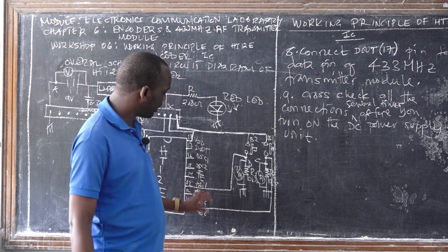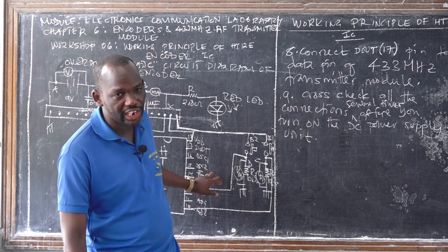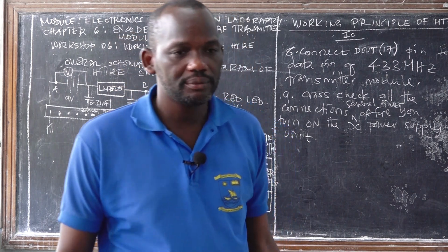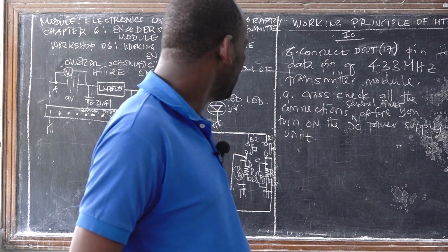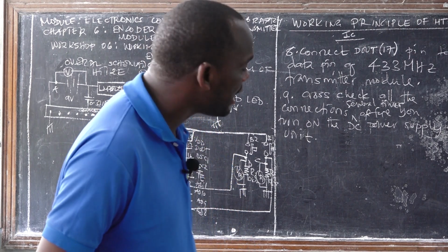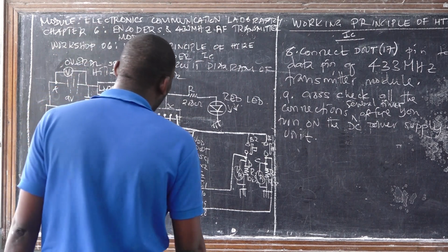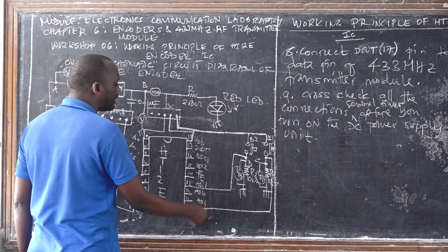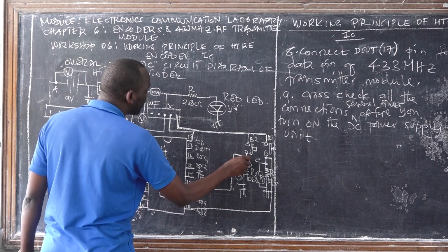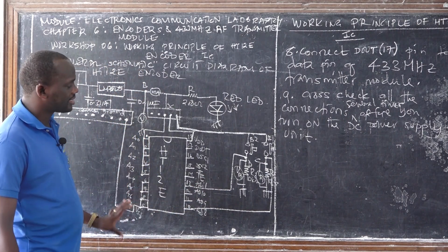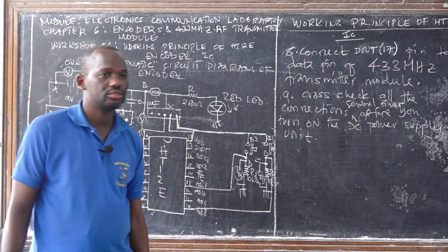For this case, we have connected our inputs AD8 and AD11, meaning pin number 10 and pin number 13. If you fail to remember this pin configuration and you reverse it in the decoder part, you will not succeed in getting the decoded information.